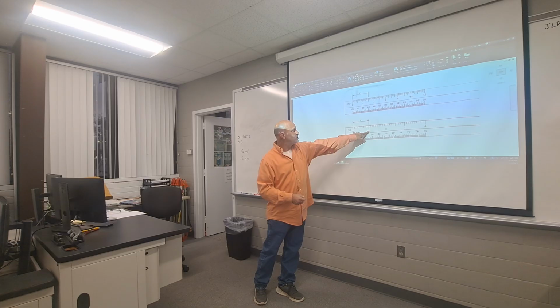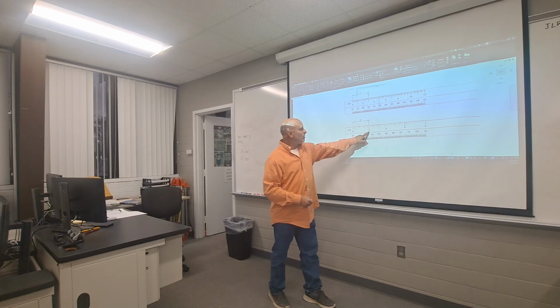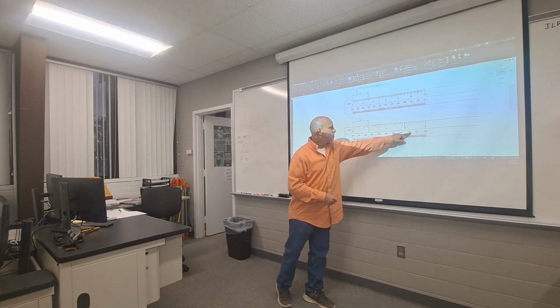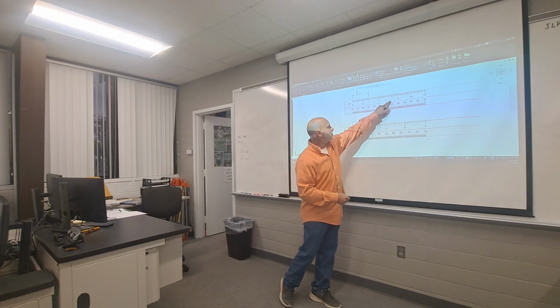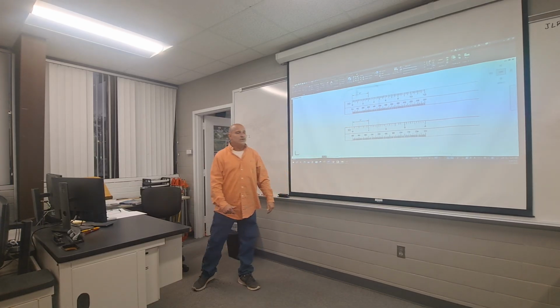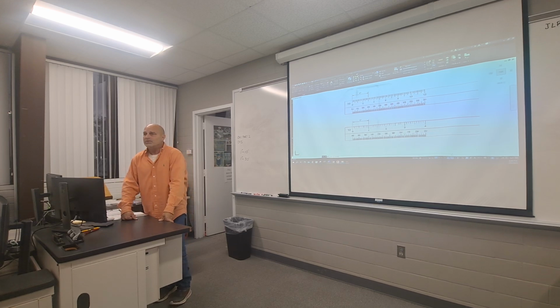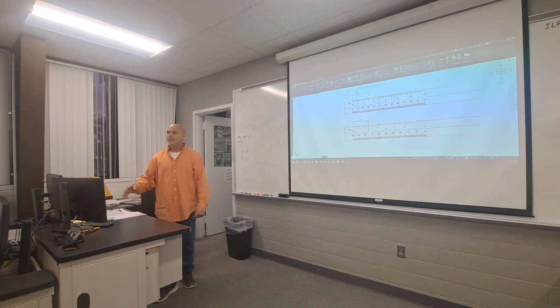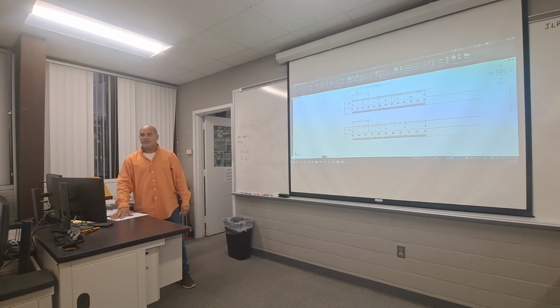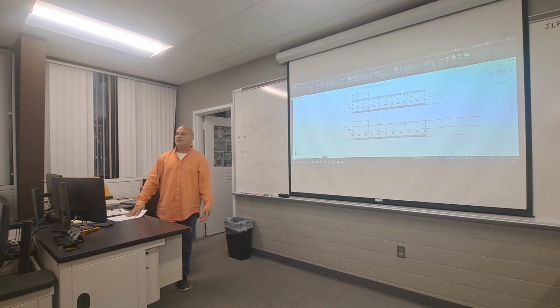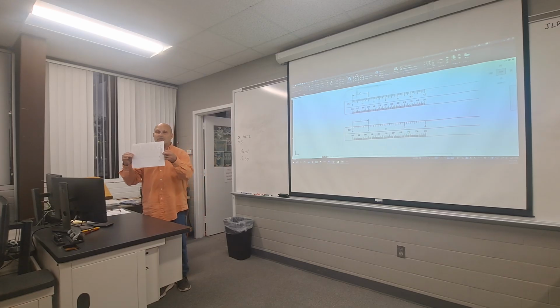So if it's 1 inch equals 10 feet, something to think about, all of these numbers that you see across here, no matter what scale, what blade you're looking at on that civil scale, that engineer scale, all of those numbers should have a 0 behind it. That's the first thing I need y'all to remember, because you're gonna be working on an assignment today and somebody's gonna turn something in with 563 feet. A line at that scale wouldn't fit on a page turned sideways, 563 feet long.